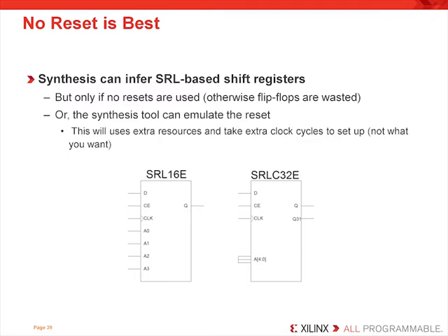You should remember that the shift register LUT does not have a reset port, so if you build a local reset into your design, you may create a problem for yourself. If you have a local reset on the shift register in your code, the synthesis tools are left with one of two choices. They either do not add the SRL primitive to your netlist, meaning they will use a bunch of regular CLB registers, which is not what you want because that will use a lot of flip-flops, or they can try to emulate the reset functionality.